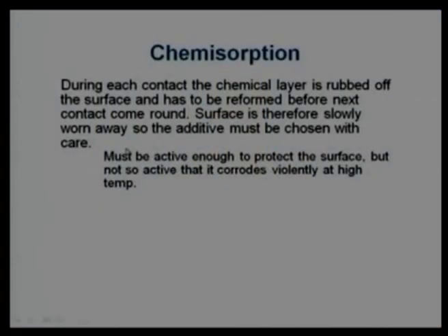So, whenever we are thinking about chemisorption, lubricant additive depletion needs to be accounted for. It will get depleted with time. It is not the case that once you add a lubricant additive, it will survive forever. It has a certain duration. After that duration, that lubricant additive will be depleted. You need to refurnish that, right? And this point says clearly, they need to have one good balance, a good trade-off. They should be active enough to protect the surface, but not too active, so that it increases the corrosion rate or the high wear rate.